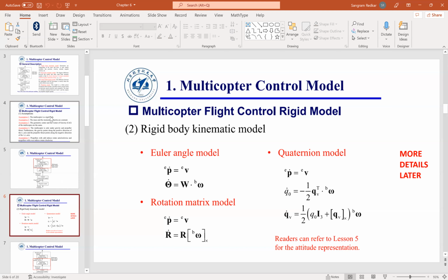Initially my body center aircraft body reference frame is at the center of gravity of this aircraft. At this point, which is zero pitch, zero roll, the pitch rate, roll rate, and yaw rate is equal to the inertial rate. Do you agree with me? Are you with me so far?